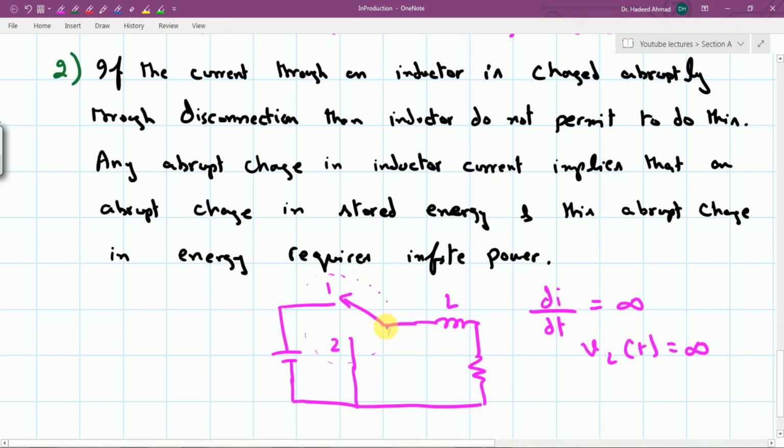However, to make these devices work within the safe limits without exceeding the voltage limits of these devices, it is always imperative to connect this pole always with the inductor, so that the inductor never becomes open circuited.